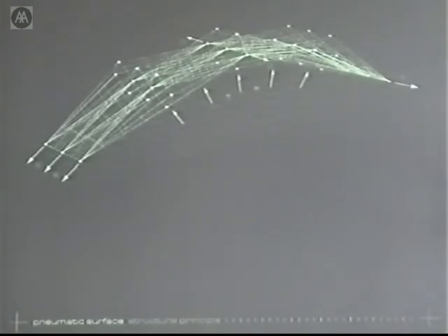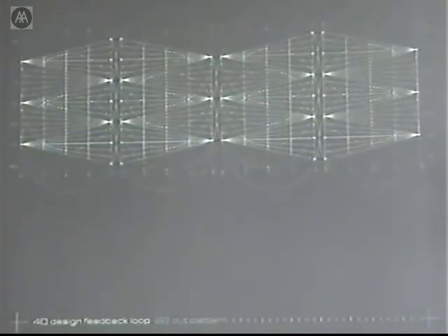And the structural principle of that self-supporting multi-chamber component is relatively simple. It's just 2 mutually stabilizing forces. One is the internal pressure that pre-stresses the membranes and forces the components into a 3-dimensional articulation because of the shorter lower seams, so the whole thing lifts itself up. And then you have the resulting tension in the seams that stabilize the system by just being pulled down to the ground. So you have two systems that work against each other and thereby stabilize themselves.